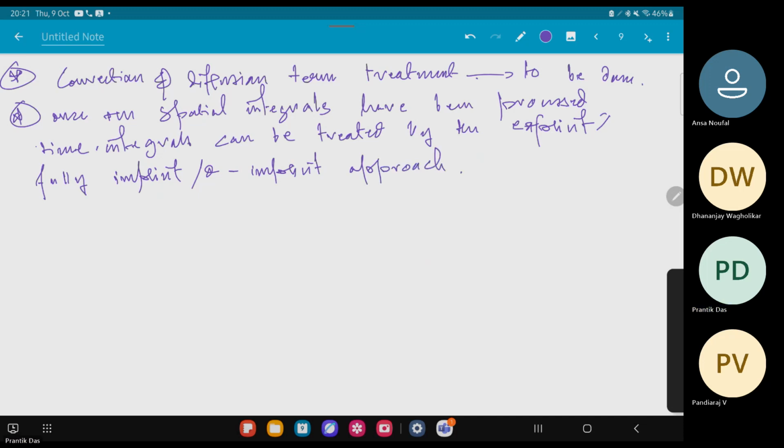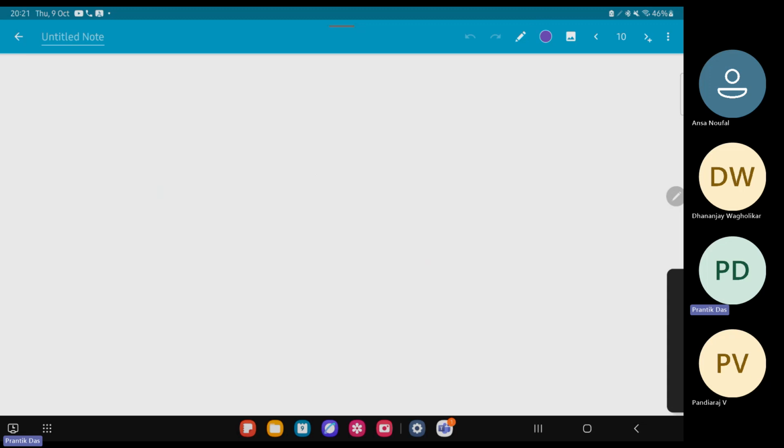Okay, so let us discuss the spatial difference. Okay, so for the diffusion term, you actually have to calculate this n_i cap dot gamma grad phi delta A_i for each and every surface that you have.